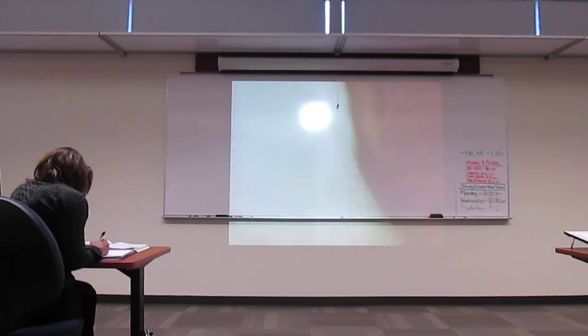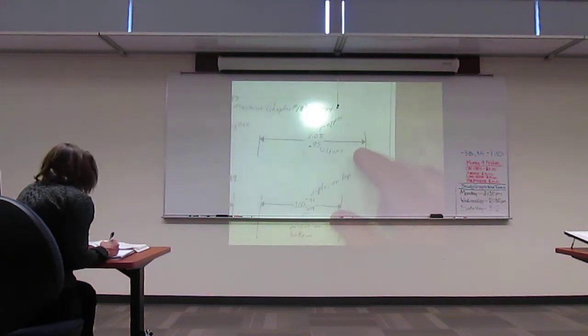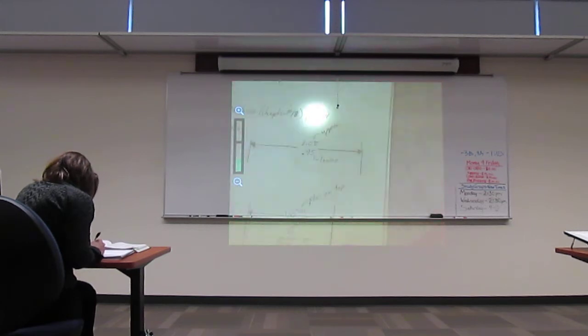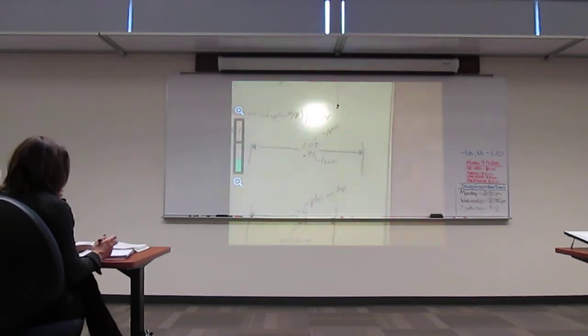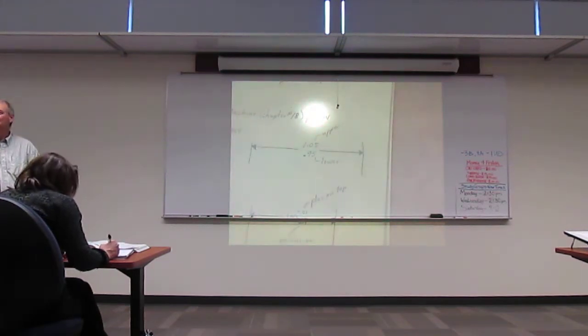Now, when we look at those, you've seen the limit. That's that one we just looked at right here, where you give the upper and lower limit. By the way, if I have an upper and lower and I'm using limit tolerancing like this one right here, what do you think the craftsman is going to try and build it at, based on the numbers I give you here? Yeah, he's going to try for a 1, right? Because that's going to give him the maximum amount of error.